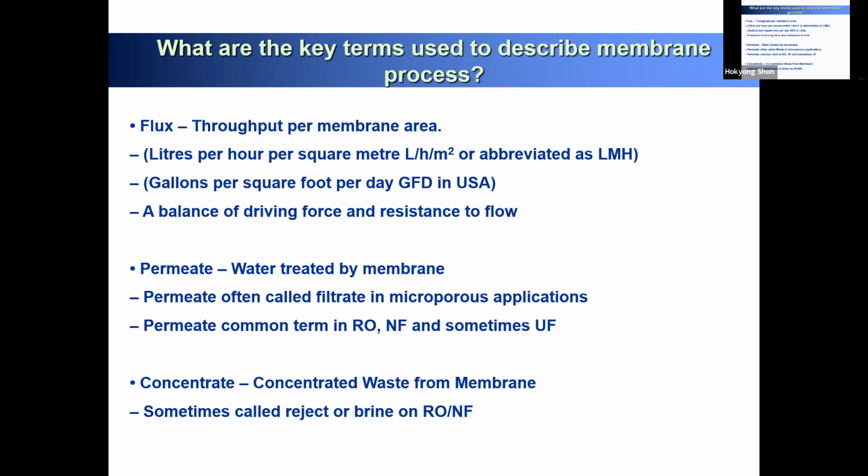Okay, we can produce, let's say, 3 LMH. So 1 square meter, 1 hour. Normally we design 20 to 30 LMH. Which means this one element multiplied by 50 by 20 gives 1,000 liter. So one element, 50 square meter, for 1 hour, this element produces 1,000 liter.